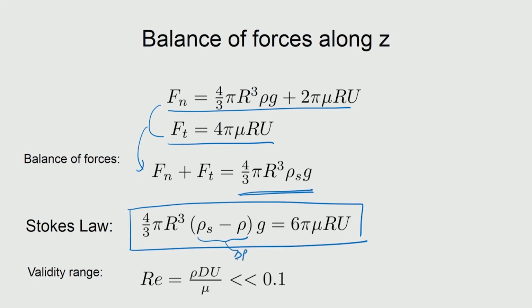Okay. So which basically tells you that because of the density difference, the buoyancy is actually compensated by a force, and that force is actually going as 6 pi mu into r into u. Now this u is then called the terminal velocity. So u is basically the terminal velocity, when this balance is happening. Okay, so if this balance does not happen, then of course you still are able to work with the fluid flow variations, but it is just that this flow pattern has not stabilized and you still have the solid body accelerating, etc. And this is also given a name, the Stokes law.